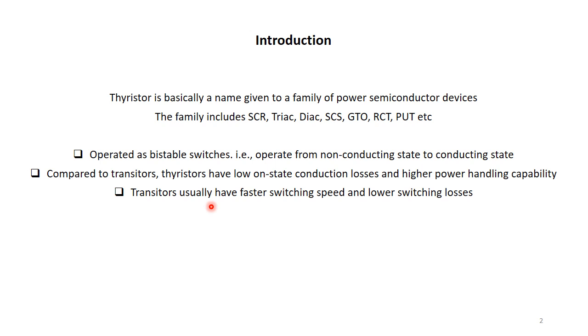It will not be wrong to say that since a thyristor is a PNPN device, it belongs to a transistor family. But compared to transistors, thyristors have low on-state conduction losses and higher power handling capability. However, transistors have faster switching speed as well as lower switching losses.